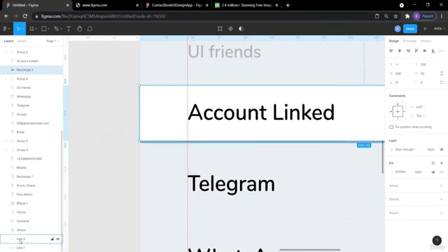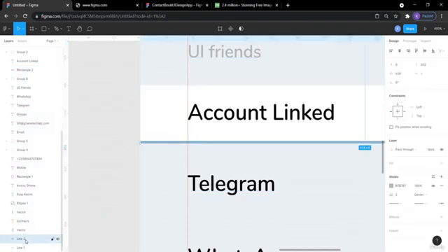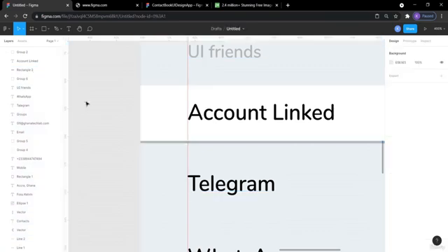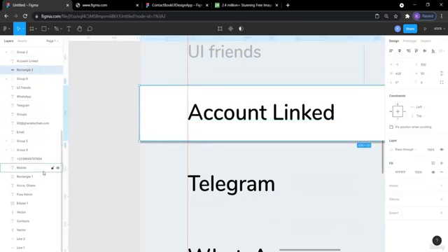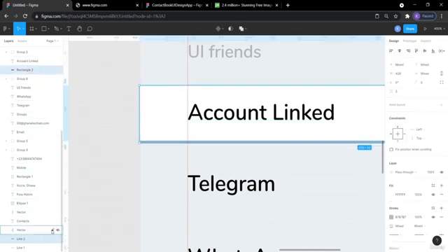Remember, we have two lines. What I'm looking for is line 2. When I click on this, it shows me that I'm actually working on this. So I'm going to select this, and then I want the rectangle. Let me select the rectangle, and then hold Control. Sorry, not Shift, Control rather. So Control, this rectangle, and then line 2. Shift is going to select all.